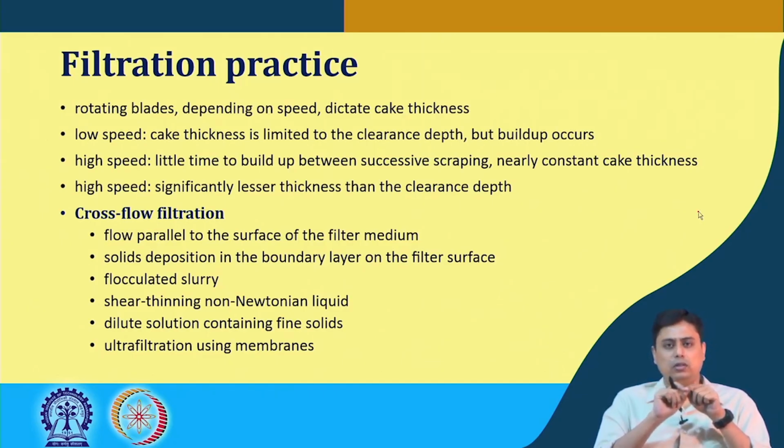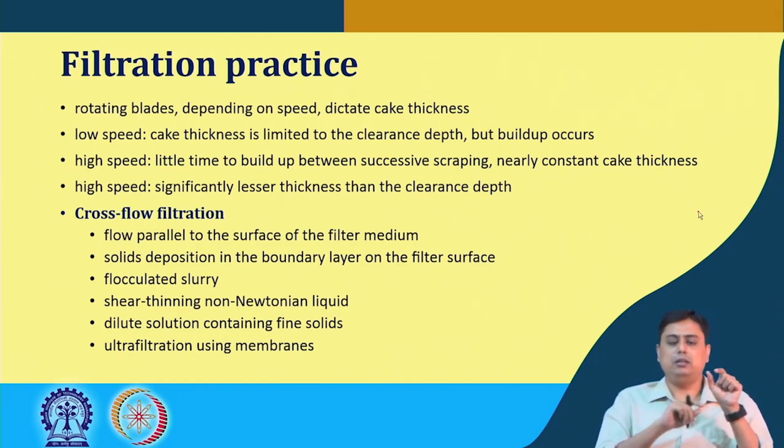So, the thickness of the cake is not exactly the thickness of the gap provided between the blade and the filter media. There is an optimization between the force that helps particles stick to the upper surface of the cake and the convective motion of the suspension near the blade.